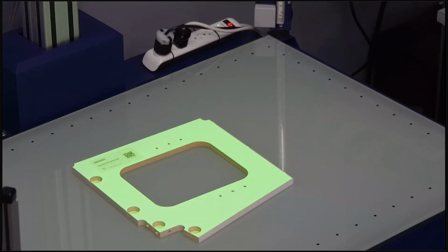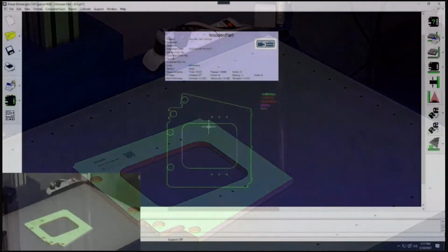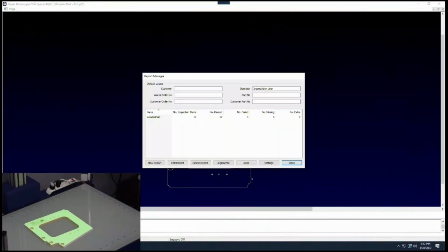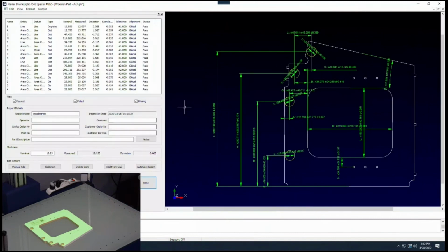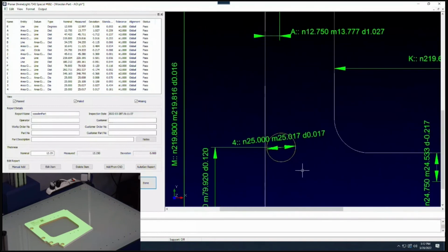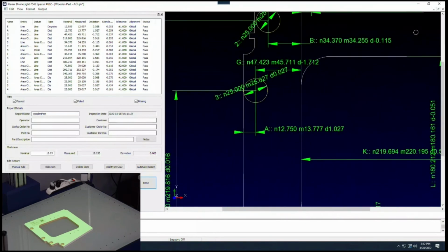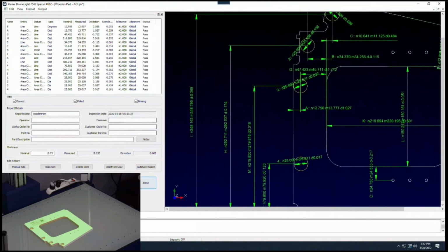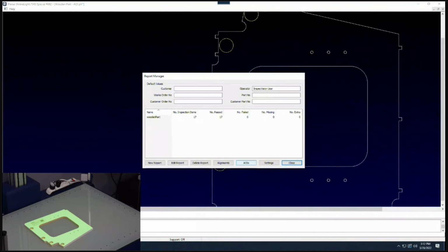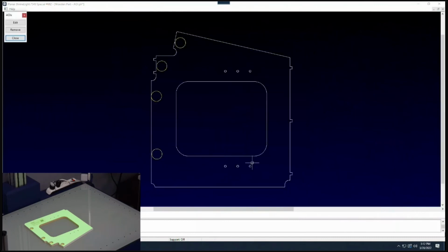Again, we're using that surf scan information, project back to the part, tell you pass or fail information. If I go to my report, you'll see that I actually highlighted X, Y locations to those holes and the diameters as well, right? So we got the X locations, the diameter, and some Y locations as well to see where those guys are at. How that works is in your new inspection reports window, if you have the AOI attached, you'll see this new guy called AOIs.